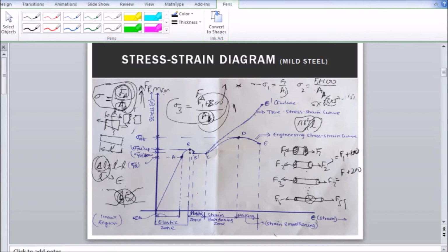That's why in true stress strain the stress is increasing very quickly. But in the engineering stress strain curve, since we are lagging behind due to use of the original area, which is higher than in every other case, in the denominator, the overall value of the fraction will be a bit lower compared to the true values. So that is the differentiation we have to understand.